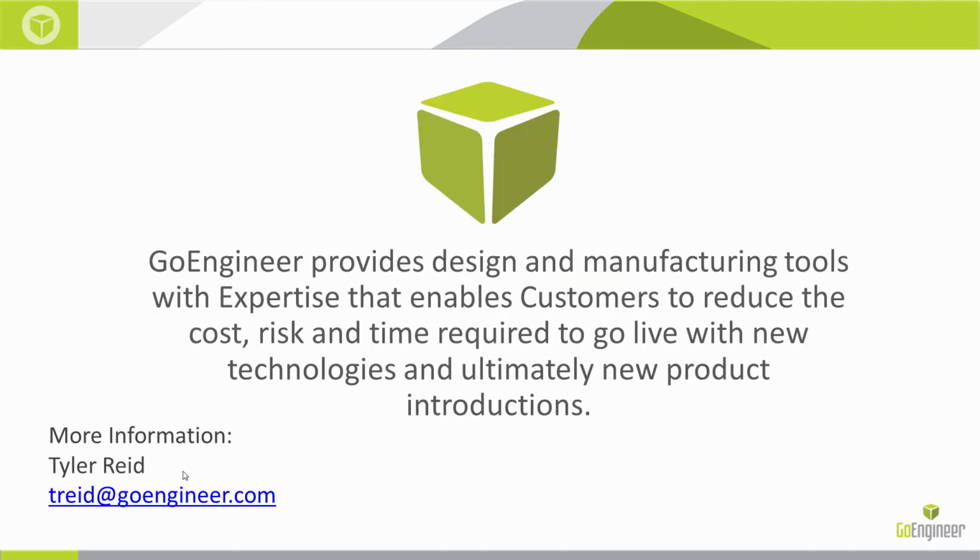So that's a basic overview of the FDM and PolyJet technologies. On the FDM side, we have thermoplastic materials, very well suited for commercial and industrial tooling and manufacturing uses. And on the PolyJet side, we have liquid photopolymers that give very aesthetic, fine surface finish, small feature models.